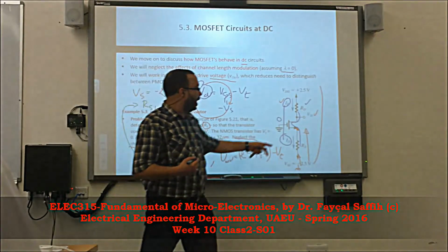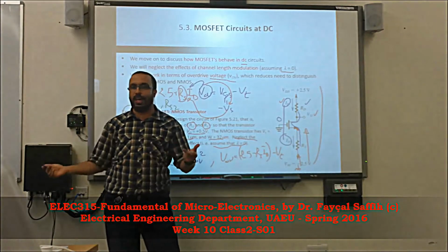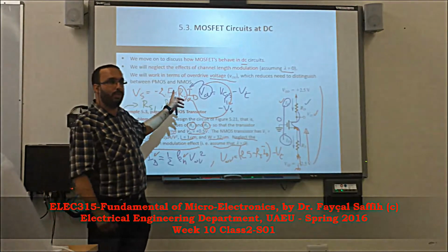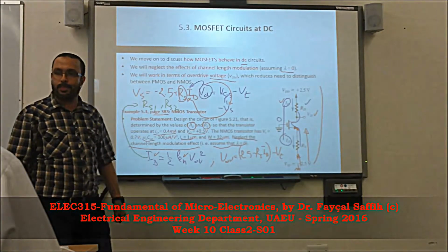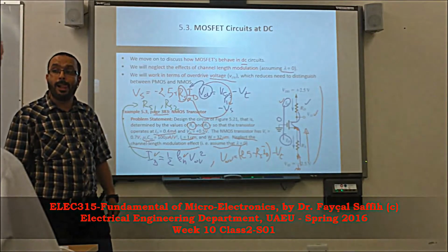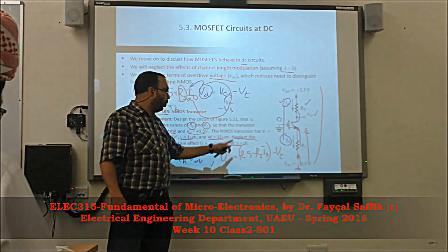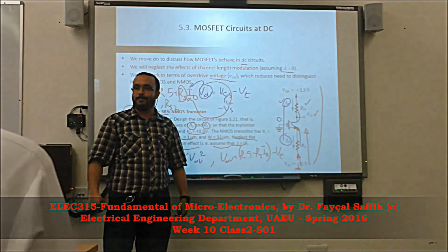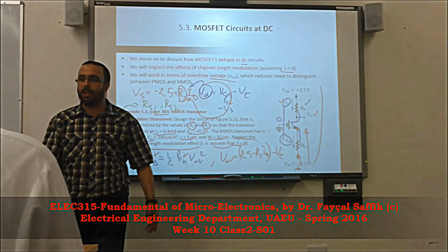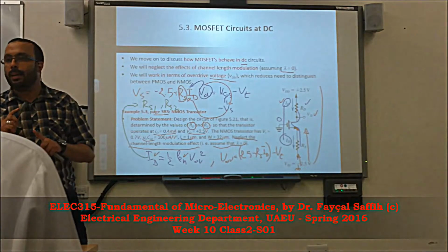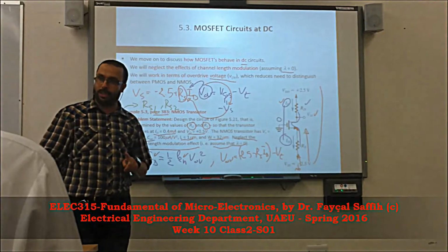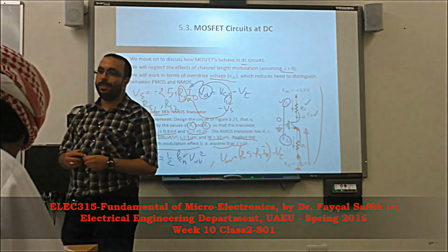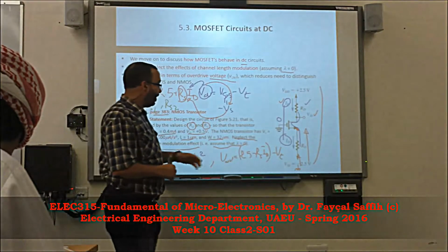And I have to make sure that VDS is bigger than overdrive, for example, to make sure that I am in saturation. So one of these assumptions is broken by one of these values of RS1 or RS2. But I can avoid this by finding the value of V overdrive. But V overdrive depends on RS, so for each RS, I have a V overdrive. So I have to check V overdrive. Who knows? Maybe they are very close values. So you have to make sure that the transistor is in saturation, and you know the condition that VDS, which is this minus this, is above V overdrive. And then it has to be consistent.